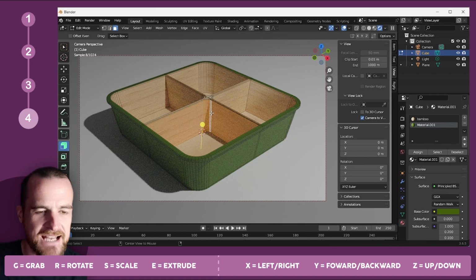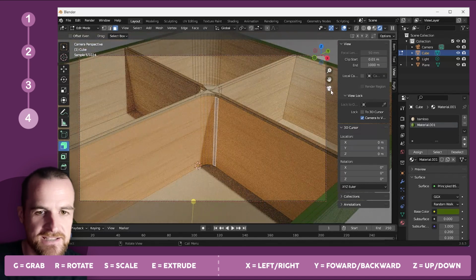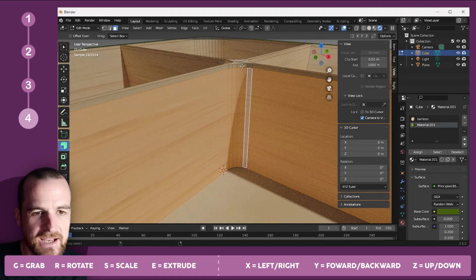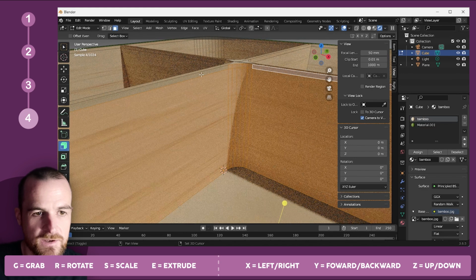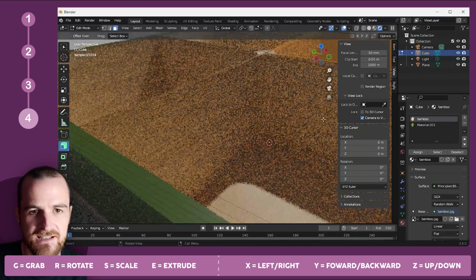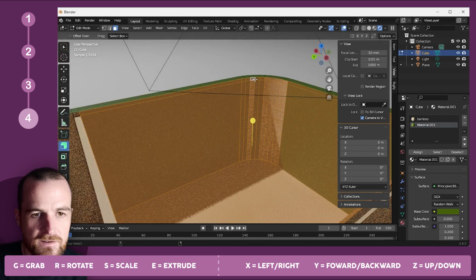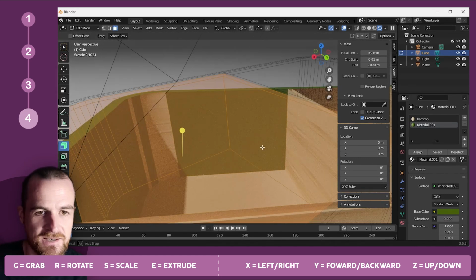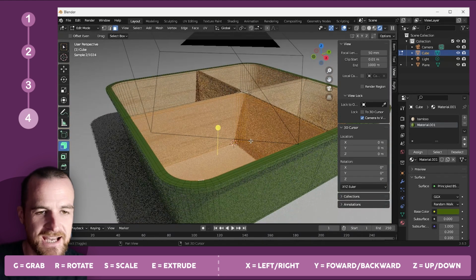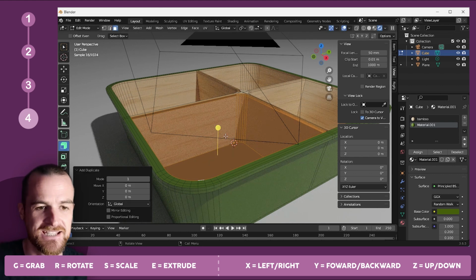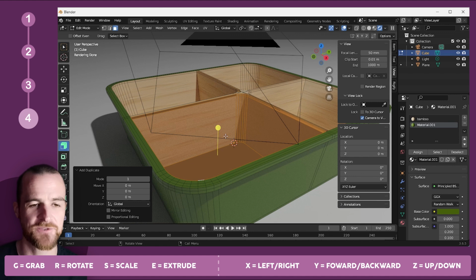So let's do that. So I've held the Alt button. So let's get out of camera mode, hold the Alt button, and I'm just holding the Shift and Alt button now to kind of collect this row as well. And you basically just want to select everything inside this bit here. So you can see, kind of collected that. Now what I want to do is I want to hit the Shift D button, and that duplicates. So do that and then hit the Enter button. So that's duplicated the faces.